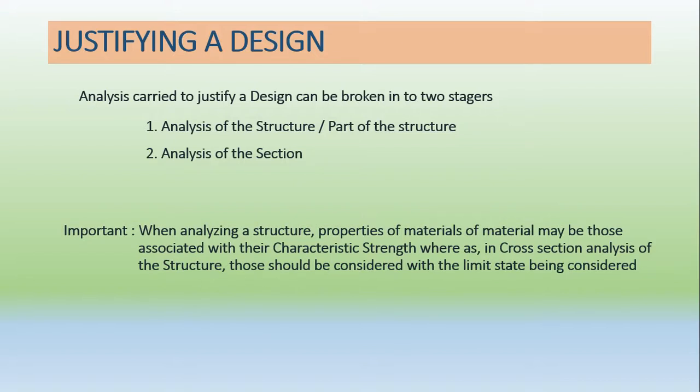So you can calculate the external load on that section according to the bending moment and shear force diagrams. You can get the maximum internal bending moment and shear forces, even axial forces. Then according to that you can check whether the provided section is adequate or not.